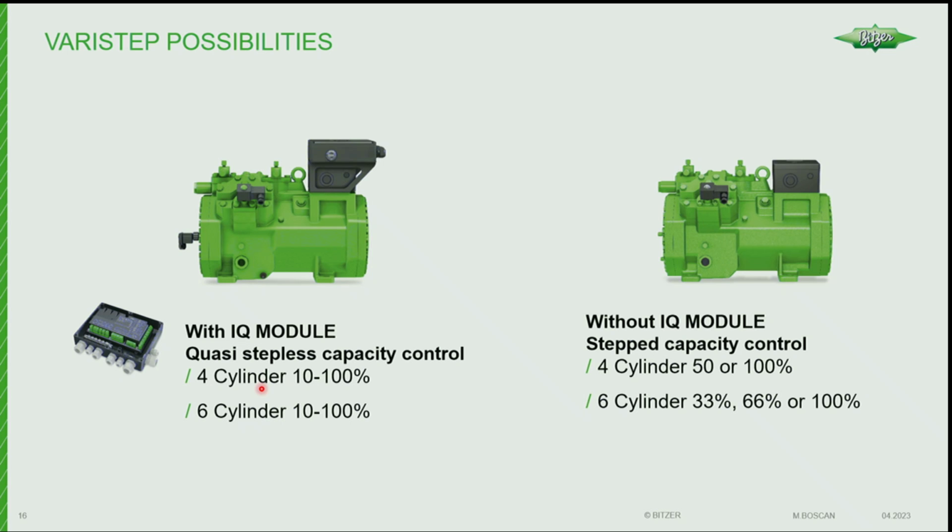And it's step control, so it's discrete, either 50 or 100. You have to just pick between the two. With the CMRC, we have an algorithm to energize and de-energize the coil to try to get to 75% or 80% or 83%. You won't be able to do that without the CM module. So for CO2, all the experience we've had so far, everybody's just going with the CMRC, because it not only controls unloading, but it does lots of other things, so there's a benefit. And then they don't have to work out their own algorithm to try to get smooth capacity regulation.